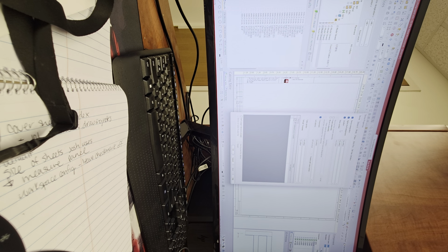In these attributes that you see down below where it says reference to master, you have a blank field. In that blank field, let's just add a new attribute. You see a drop down menu that appears. The attribute that triggers something to be excluded from BOM is called no BOM. So just scroll down to the N section, and there should be a no BOM option. And as a value on the right side, it's just a 1 or 0.